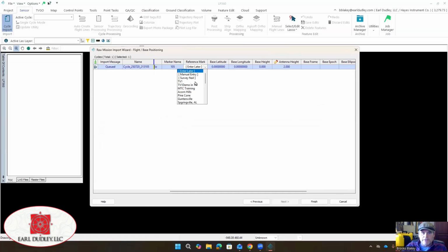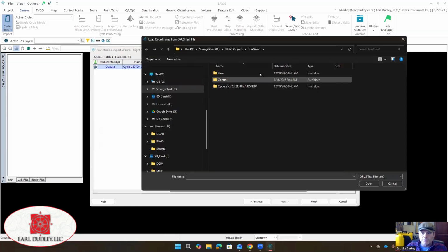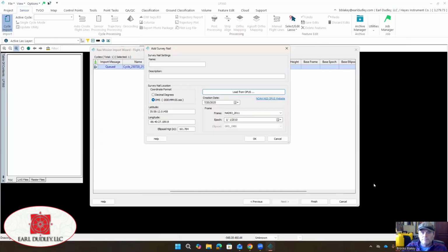Everything looks good there, and we can go ahead and enter our survey nail right here. Now I did an OPUS solution, so I'm going to go find my OPUS. And we're just going to call this TrueView 1 LP360 demo.